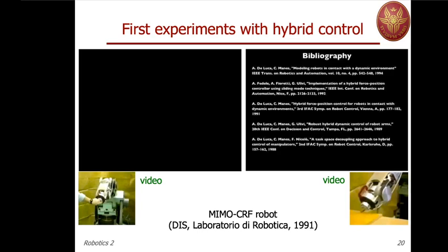So the fact that we still achieve the desired velocity and follow the position of our trajectory on the plane, despite the presence of this extra force, is thanks to the controller in the motion direction that rejects this force disturbance. And of course, something similar happens in the complementary direction. Indeed, however, we will see that this information can be used to make things better, to estimate online the fact that the orientation of the surface has changed, and possibly also continuously.